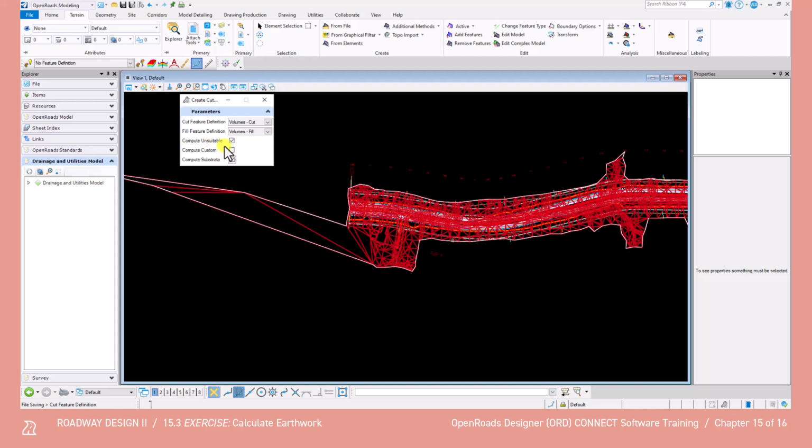And then toggling on these two will calculate the existing pavement and exclude any topsoil from the cut and fill calculations. It also includes the existing rock layer as a separate cut volume, since the existing rock surface feature definition is set to have the substrata volume option. The software will know that the mesh is the substrata. And then we can left click through some prompts. Earthwork will take some time to process, so be patient.